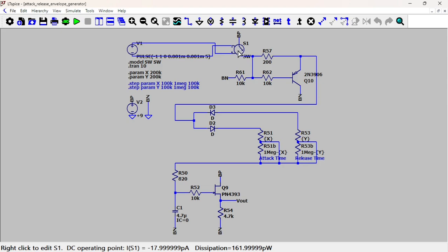It's the same thing. So when the switch is off, it's at this voltage here, because this is B positive, which is I think 9 volt. So when the switch is on, you get 9 volt here, otherwise you get 0. Actually, this circuit is very simple in the way it works.